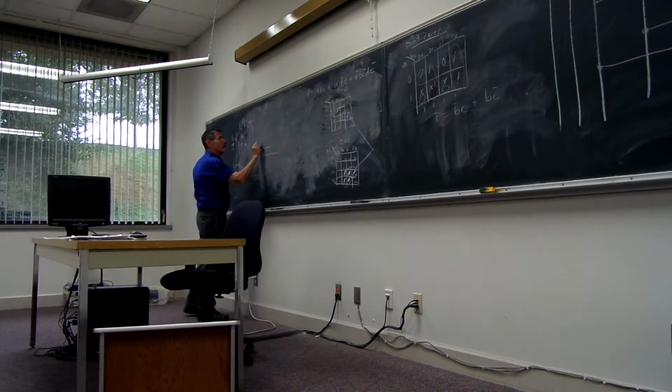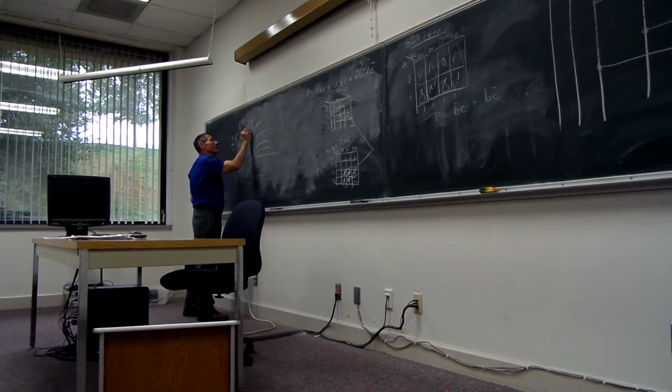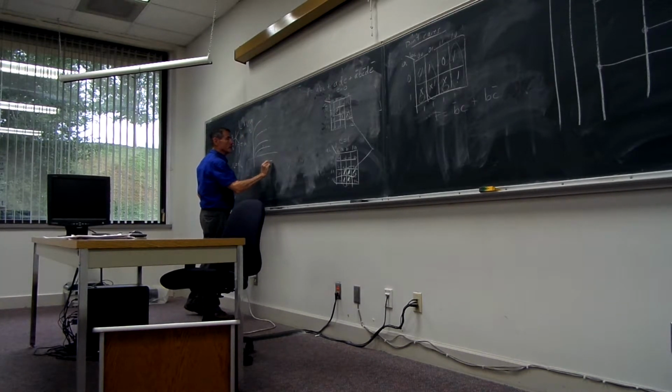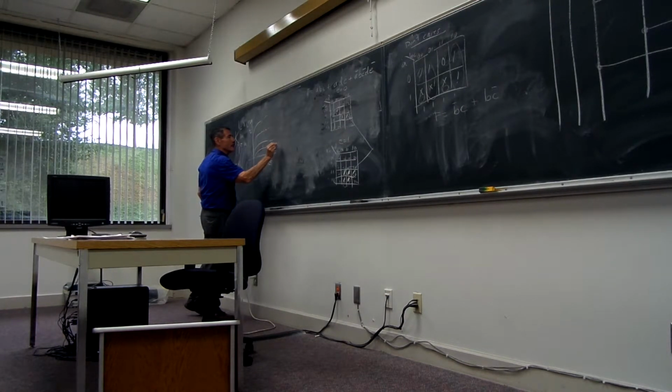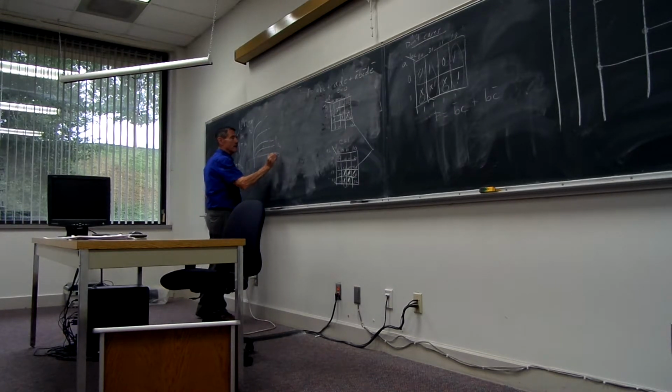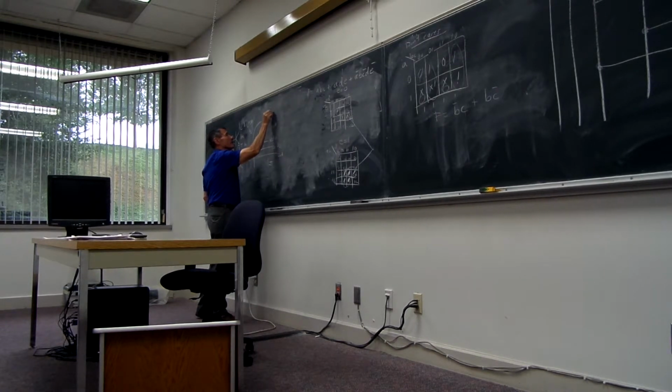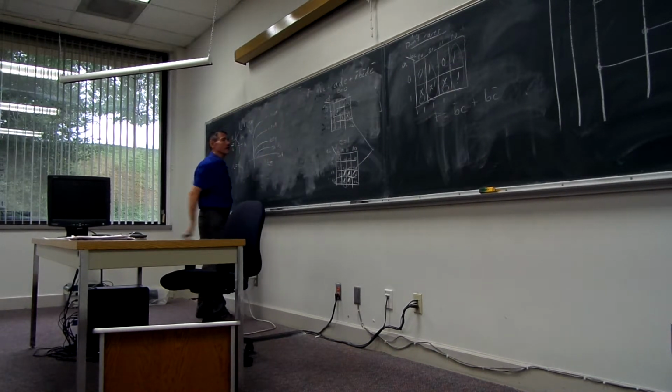We've got a family of curves. This is our collector current, this is the collector-to-emitter voltage, and this is the base current going up here. So this may be 0 microamps, 10, 20, 30, 40 microamps, something like that.